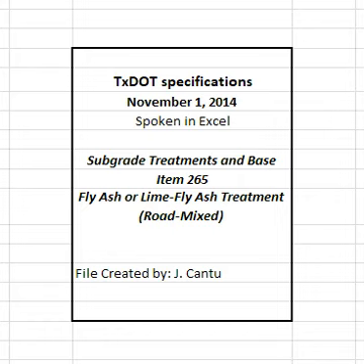When repulverization of the failing section is not achievable, remove failing material and replace with acceptable treated material. When density control is specified, determine a new maximum density of the reworked material in accordance with Tex-127-E, and compact in accordance with Section 265.4.4.2, Density Control. Compact as directed when ordinary compaction is specified.